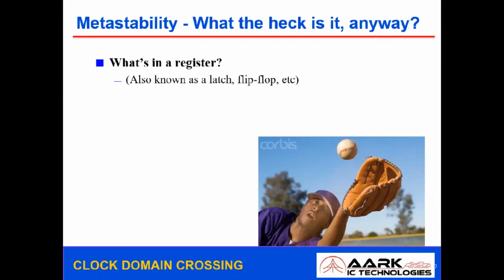Now in this context, I have used a register. A register is well known as a latch or a flip-flop. Here is another important point that I want to address, because most people, even from post graduation, get confused about the basic difference between a latch and a flip-flop. Most of them will say that a latch will have an enable and a flip-flop will have a clock. I'm sorry to say that both latch and flip-flop are triggered with a clock only.